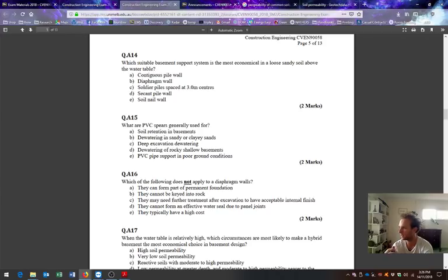How deep can steel reo cage go in a bored pile? As deep as you can drill the hole, because you can just keep lowering it in. So there's no literal limit on bored pile reinforcement. The Eureka Tower has fully reinforced bored rock socketed piles down to a depth of 55 metres, for example.